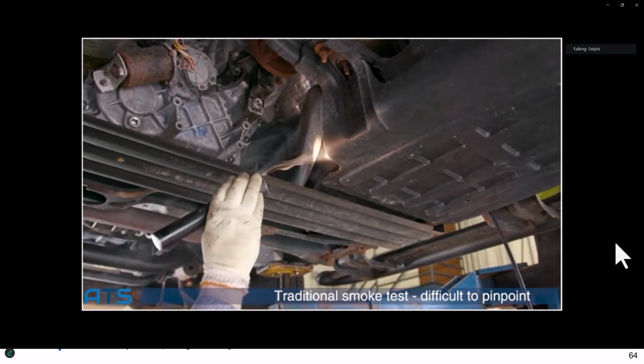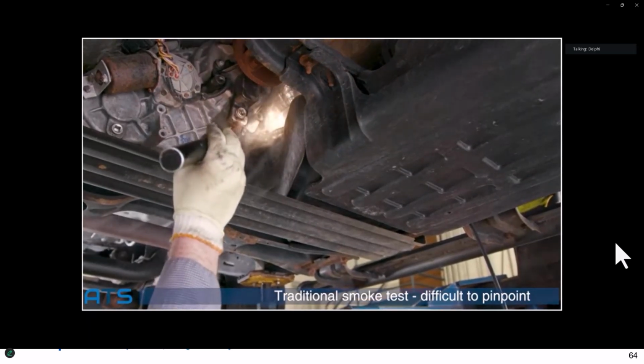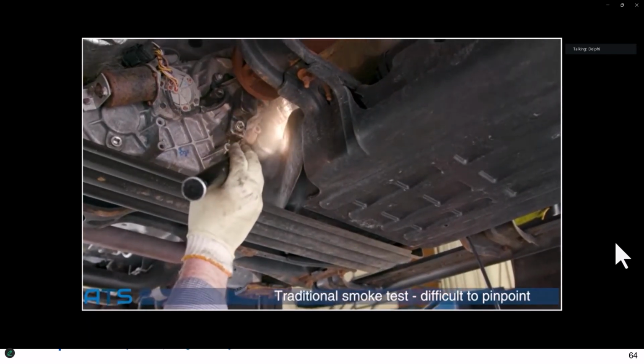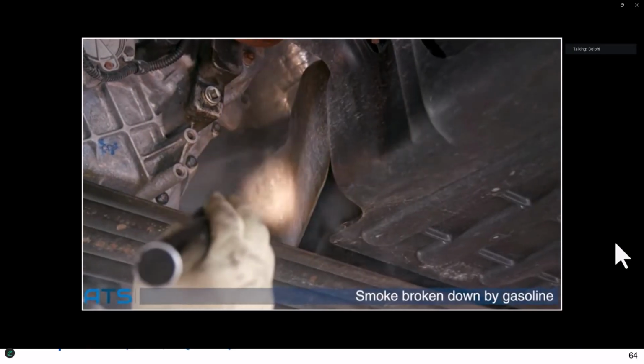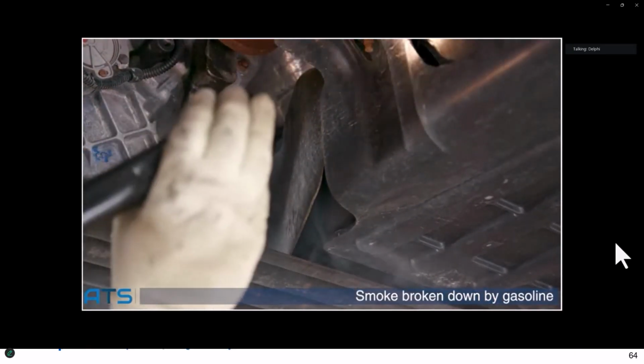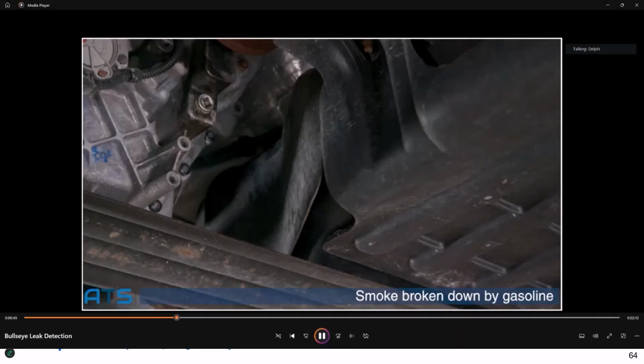Traditional smoke testing can be a challenge. Either the smoke escapes in such a volume that the source is hard to pinpoint, or the leak is so small the smoke is undetectable. Yet another problem for smoke is it is an oil base that is heated into a vapor. This vapor is made up of hydrocarbons. In chemistry, likes break down likes. In other words, the gasoline being a hydrocarbon base will break down the smoke. Thus, no smoke will be present at the leak site.